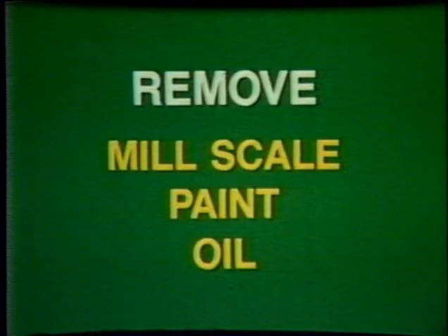Failure to remove mill scale or other surface coatings such as paint and oil will prevent the molten metal from fusing properly. The single most common cause of overlap is an excessively large weld puddle which can flow ahead of the arc.